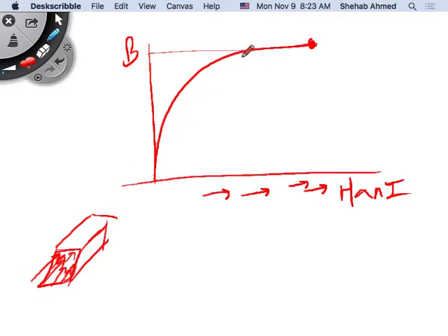So you typically want to operate in a region where increases or decreases in current are changing the amount of flux in the core, so you are changing the amount of flux or stored energy that you have. Otherwise, if you keep putting more current, you're burning copper losses and not getting any additional flux for that, right?